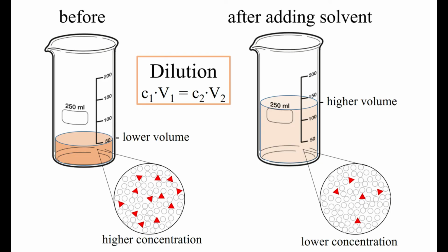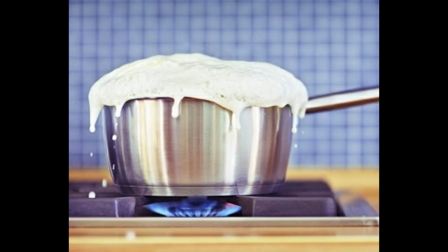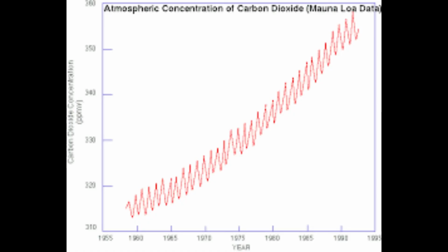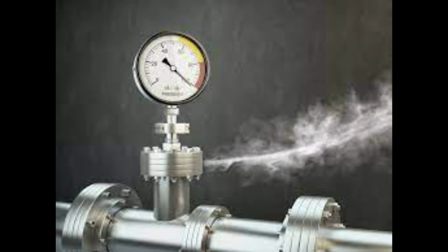One example of moderation is dilution. Dilution reduces the hazard associated with the storage and use of low boiling hazardous material in two ways. Number one, by reducing the storage pressure, and number two, by reducing the initial atmospheric concentration if a release occurs.